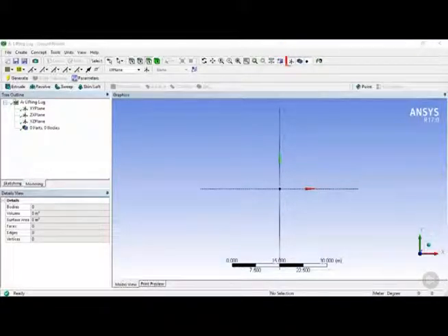Next we have the Display toolbar. So here we have the Display plane. This allows you to toggle between displaying an axis, vectors, and origin point. Next we have the Display model, which allows you to toggle between displaying the 3D model or not. If you turn off the 3D model, the plane is turned on automatically. Then next we have the Display points, which allows you to toggle between displaying the points generated by point features in the model or not.